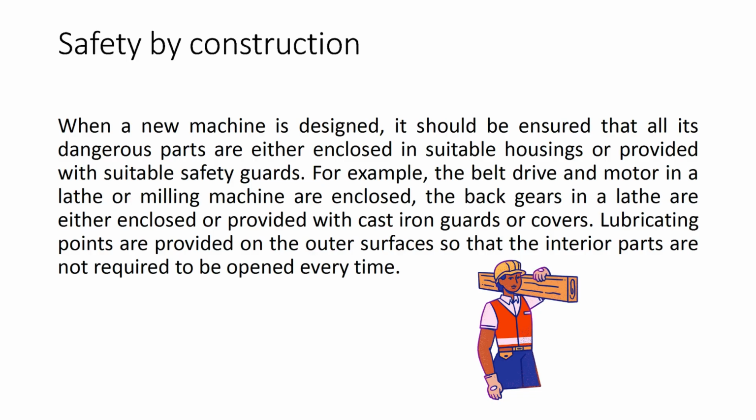When a new machine is designed, it should be ensured that all its dangerous parts are either enclosed in suitable housings or provided with suitable safety guards. Think about the belt drive and motor in a lathe. They are enclosed. Lubricating points are on the outer surfaces, so we don't have to open the interior every time.